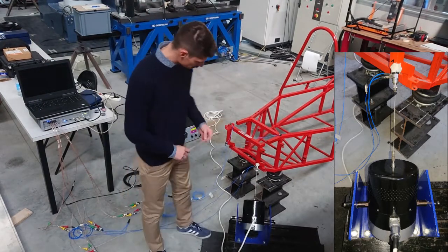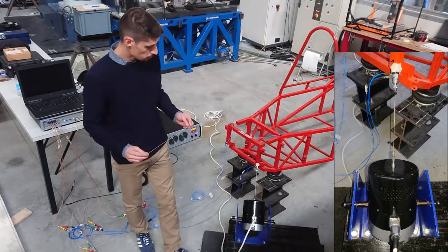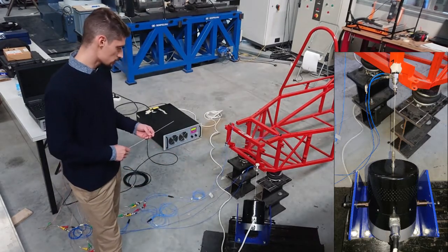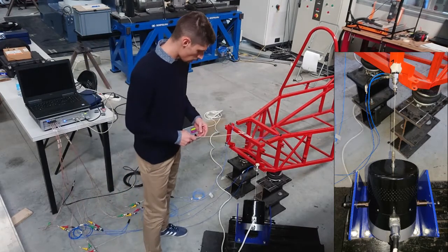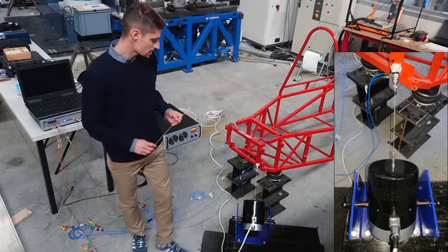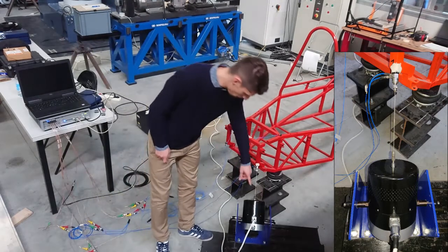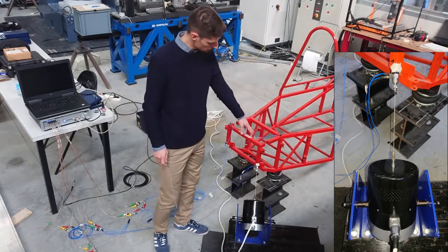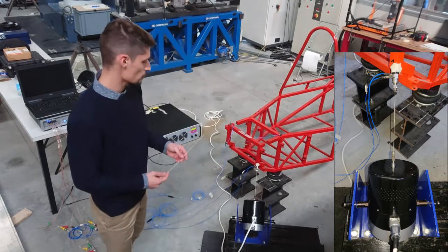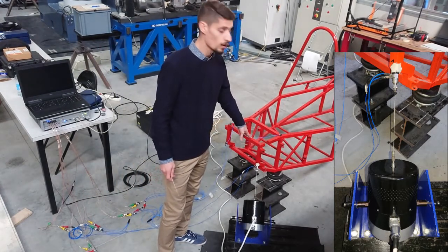The stinger is the element that connects the shaker to the structure, and it plays a crucial role for a good modal analysis. Because try to imagine that you directly connect your shaker to your structure. In this case, you probably introduce the dynamic effect of your shaker into the dynamic of your structure, and therefore you could compromise your result, and you could alter the FRF of your structure.